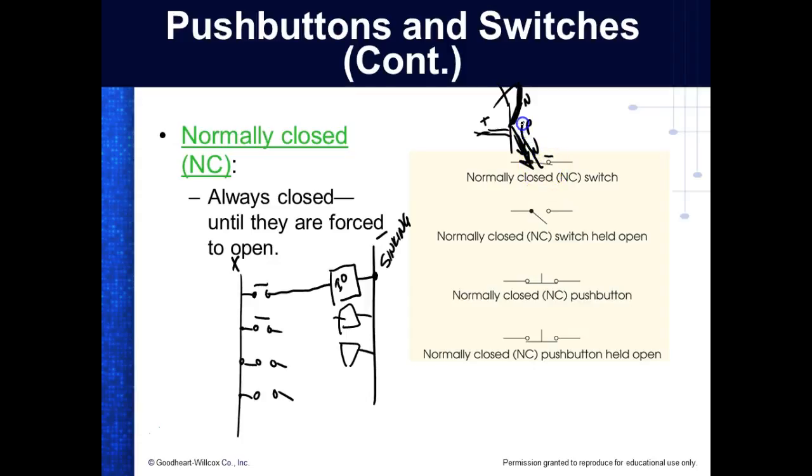So a transistor is a current valve. That's all it is. Everybody know how a water valve works? What can you do with that water valve? You can turn it a little bit on, a little bit off. So we can operate it both ways. In amplifiers, we operate it in between. If we're going to use a switch, we either turn it all the way on or off, and so we call it saturation and cutoff. So that's what we do.